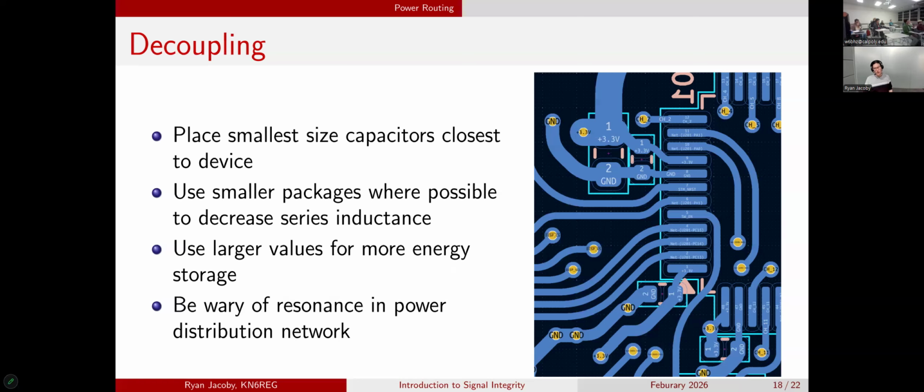Yeah, so when we see sudden changes in the amount of current being drawn on the power supply, the voltage will fluctuate, right? So if we go to send a 1, we have to switch a MOSFET from the off state to the on state, charging up that gate to change the MOSFET state, and the current required to drive that line high will cause a little tiny fluctuation.